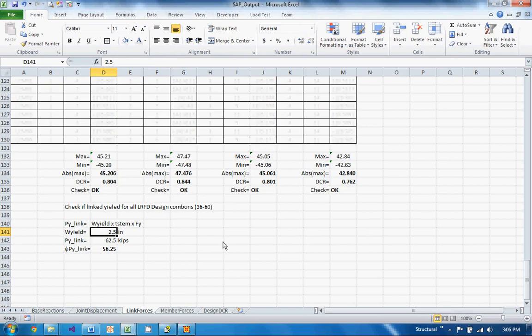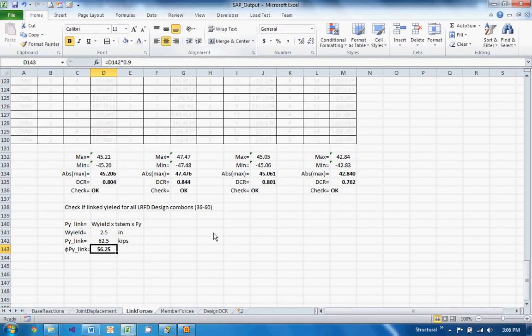Remember, every time you change this, you have to rerun it again. Your stiffness changes. You see how many iterations this is going to go if you don't start off with a good one. So okay, 2.5. We'll say at the end we'll go back and run it in SAP instead.